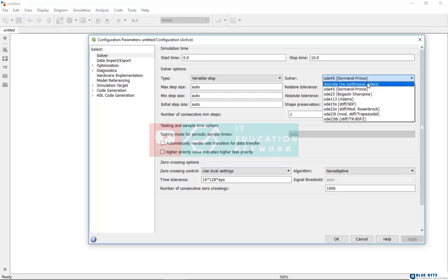Just here, I want to tell you that in the default mode of Simulink, this type of solving is on ODE45. This is the default mode. But the best one is ODE23tb. It both decreases the simulation time and its accuracy is almost the same as other methods. This method is common among users because the simulation time decreases.